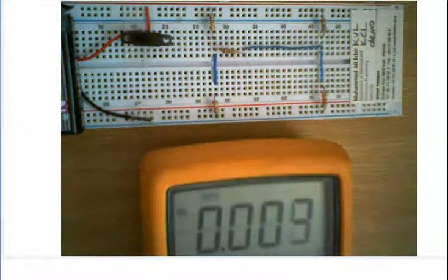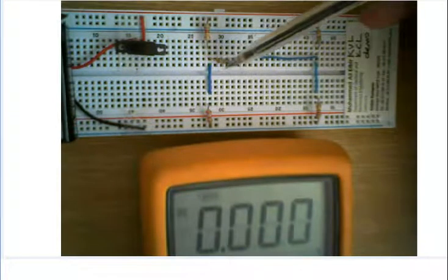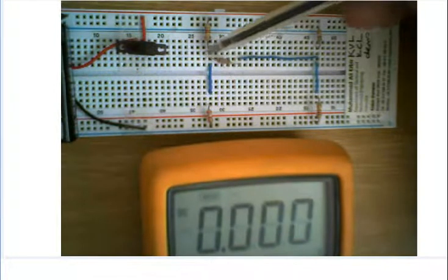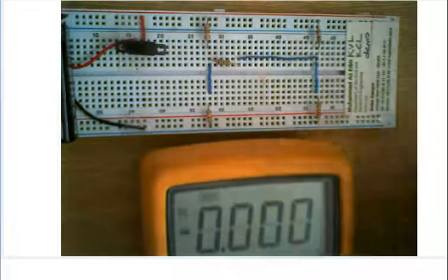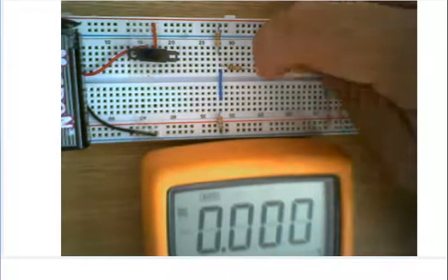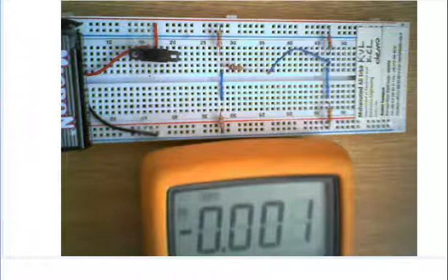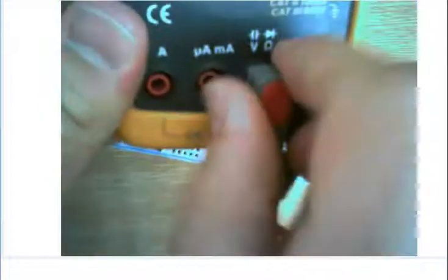And if you want to read the current of a resistor, for example, I will measure the current of this resistor, and it's flowing from E1 to E2, in this direction, from left to right. I have to open the branch. Now I have opened the branch. There is an open circuit here, and I have to change the adjustment of my multimeter to milliamp measurements. Now it's in the milliamp adjustment, and I have to change the probe to the milliamp port as well.